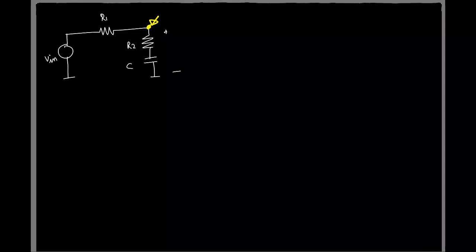Output is obtained as a sum of two different voltages, and these two voltages have different phases, right? Because one is a capacitor voltage, one is a resistor voltage, and this indeed has a zero. So again, to find it, you can just do KCL, right? So I have, let us say, I of S. So basically what happens is I of S flows into R2 plus 1 by SC to give you 0, isn't it? I mean, this is the sum of the two voltages.